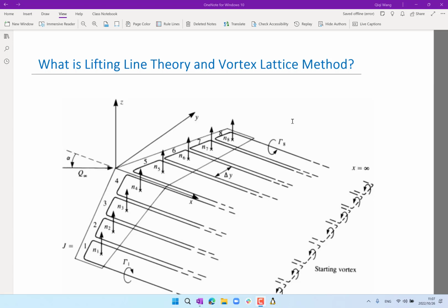For example, instead of calculating the induced flow on just the 4 locations, as we did on Monday, if we calculate the induced downwash everywhere, as a function of the y location, so this is the y-axis, and we perform an analytical integration, we can actually figure out what kind of wing would minimize the amount of induced drag for a fixed amount of lift.